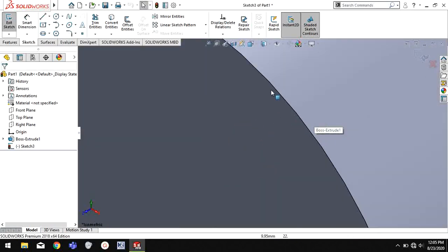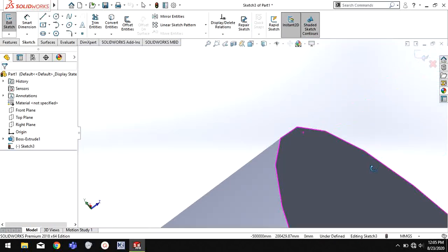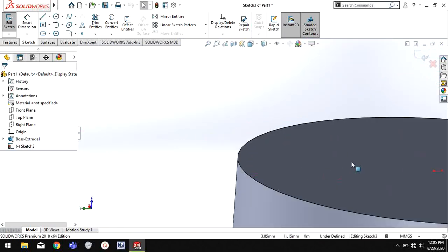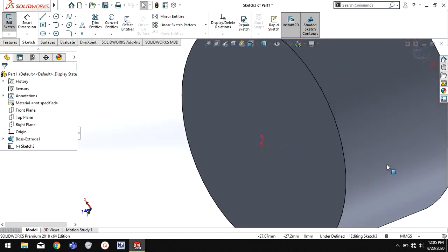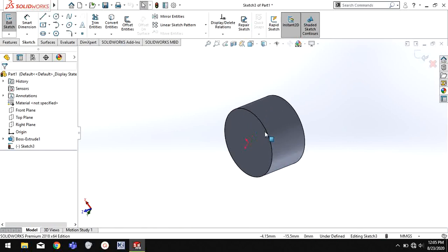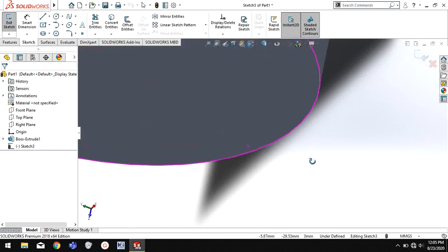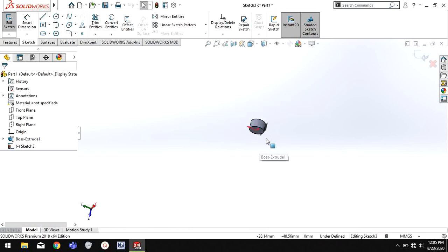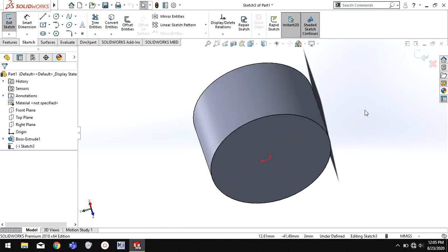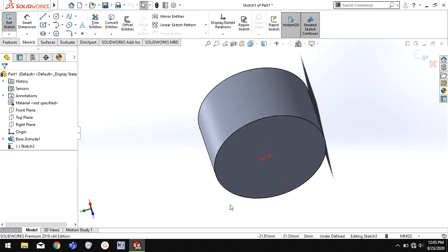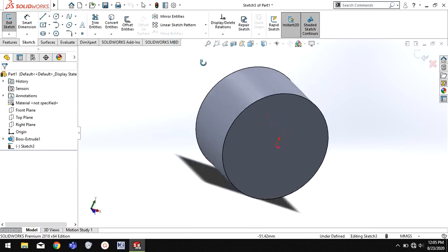And sometimes when you're very zoomed in on your component and you rotate it, it just vanishes off the screen, and no matter how much you zoom out, you are not able to find it. That happens sometimes in assembly or something. Suppose assume that my component is off the screen. Now I'll just press the F key and I'll get my component back in the screen, no matter where it is, even if you cannot find it. The F key will get it back to its place. So this helps me sometimes.